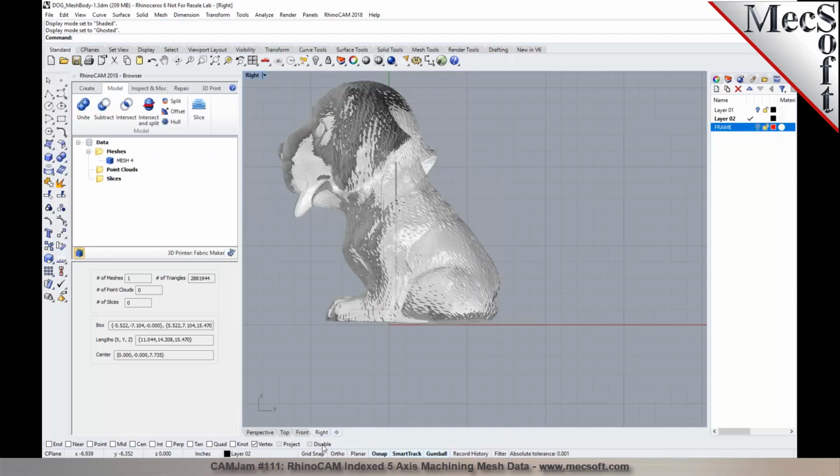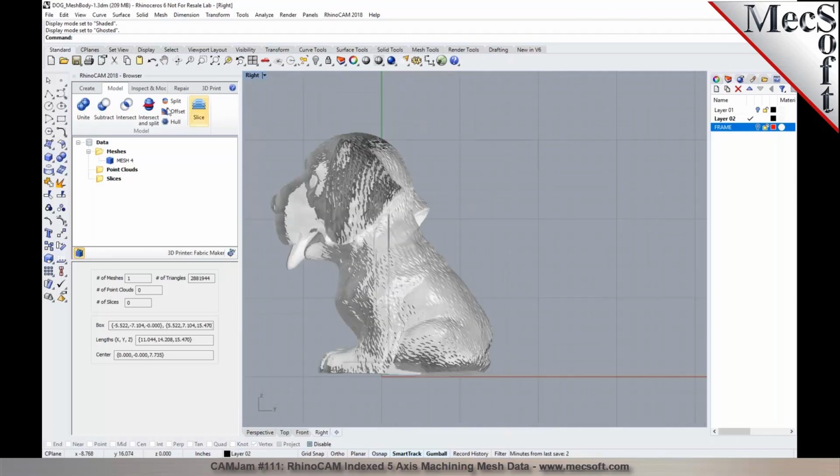Okay, and I can actually go ahead and create a free-form curve in Rhino, right? Let me say I want to take a free-form curve, and I'll just throw in a free-form curve in here. I'll disable all the snaps in here. Absolutely. I can model something like this in here.